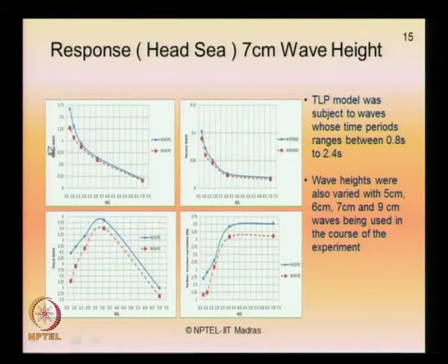in the surge degree, whereas in the heave degree, since the damping effect is not predominant, you will see that even at lower H by L values the effect is not significant. In case of pitch, of course the effect is significant and the trend remains the same, and the maximum reduction occurs at a specific value of H by L, which is seen as a coupling effect between the heave and pitch degrees of freedom.